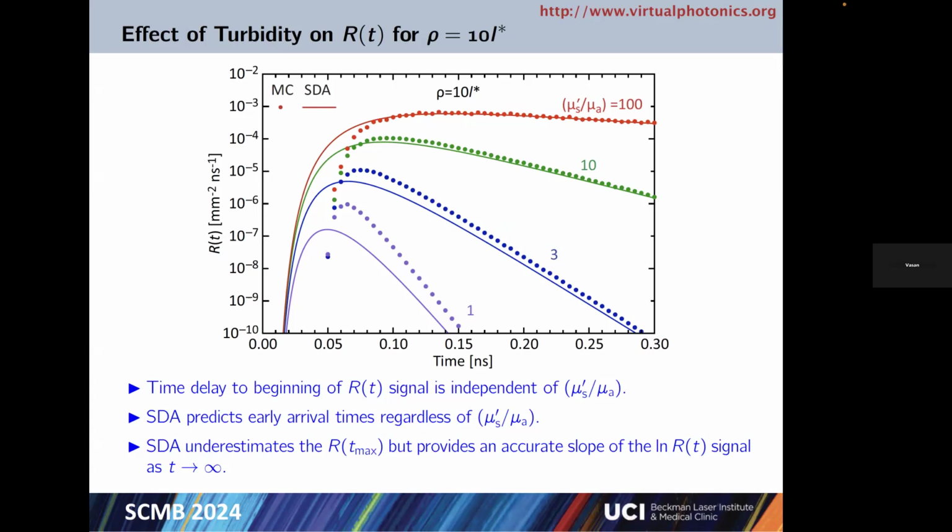Oh, okay. So there are a couple of different ways you can do this. I mean, in reality, you don't use those two simple equations. Some people say, okay, I know my instrument response function, I can kind of deconvolve that out of what I measured to try to approximate what the signals would look like without the instrument response.